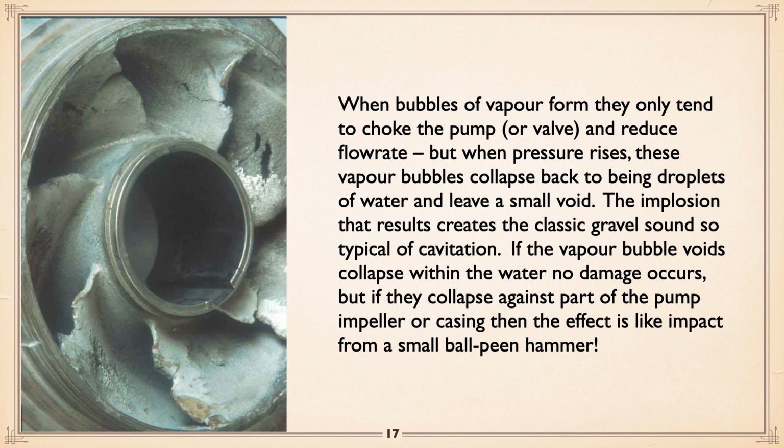And the only effect, again, is it chokes flow, much like vortexing does. But different from vortexing, if those little vapor bubbles happen to be up against metal, any part of the pump, when they collapse, it's like a little ball peen hammer. It's a fairly distinct little thing, and the higher the pressure, the worse it is. Although the higher the pressure, less chance of vortexing.